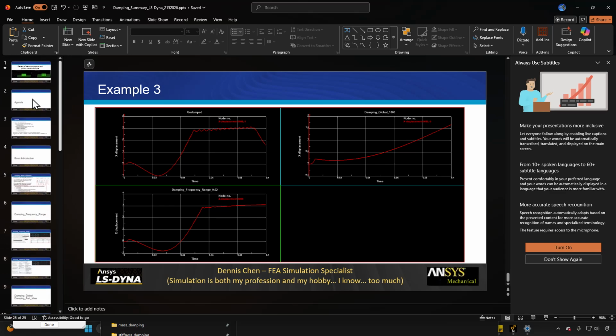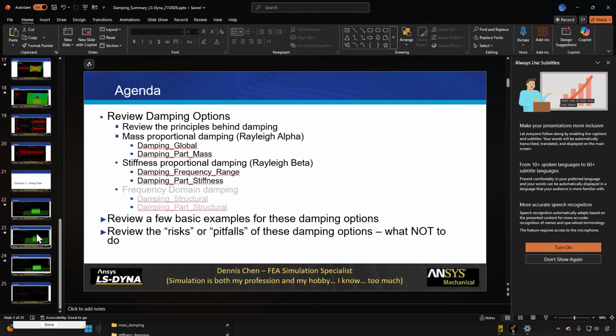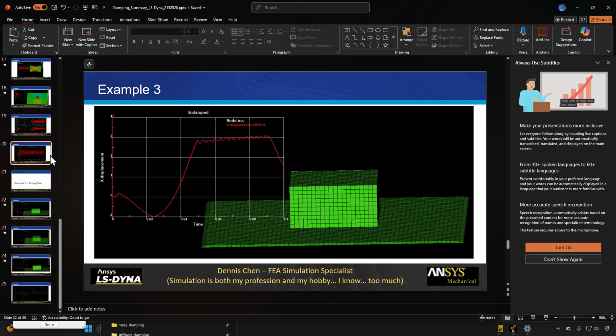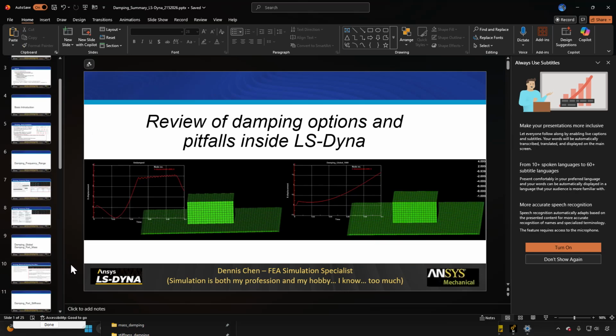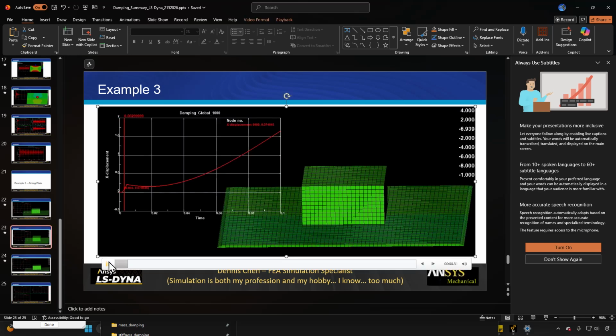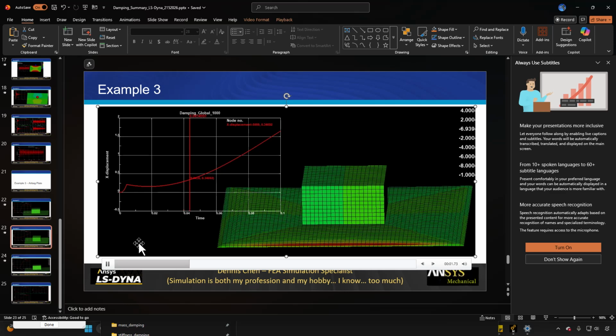Now remember, damping is a pretty easy concept to understand, but it's actually pretty difficult to get right inside a real model. So in most situations, I like to just underdamp it, because if you overdamp the system, you basically completely ruin the analysis, right? Such as in this airbag example, for instance. So we want to damp just a little bit to reduce some noise. If you can live with not damping the system at all, then don't damp it at all, because that does a much better job in a lot of ways, where you don't lose any accuracy.